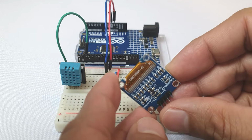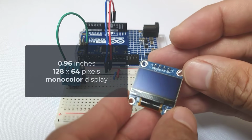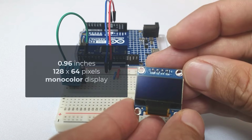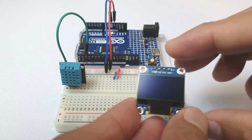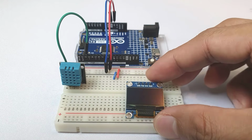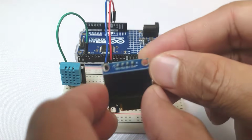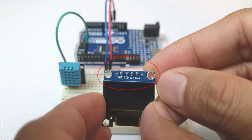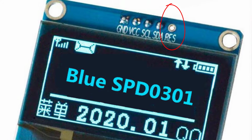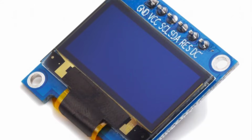Now, this OLED display that I'm using is a 0.96-inch screen, 128 by 64 pixels, monocolor display. However, if you have a different screen size, such as the 1.5 or the 2.5-inch versions, the connections to the Arduino are the same. This model has only 4 pins. However, please note that there are models that come with an extra reset pin. There are also models that communicate using SPI communication protocol instead of I2C.